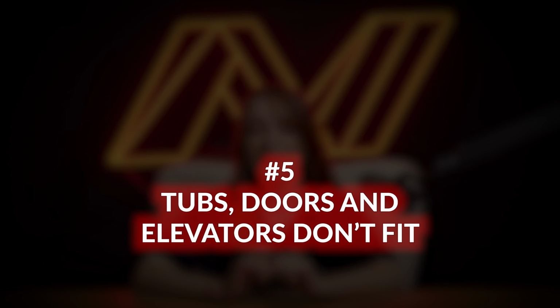And now we're coming to one of the most common disconnects between designs and real-world installations. Tubs, doors, and elevators don't always fit. Drawings often use typical dimensions for tubs, doors, and elevator shafts, and in the early stages that makes sense.